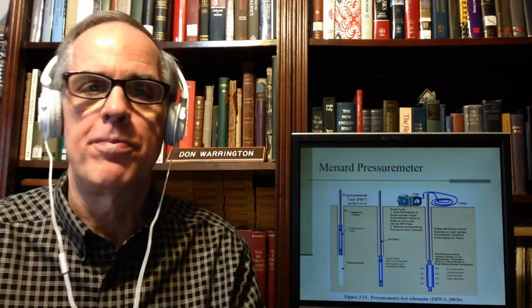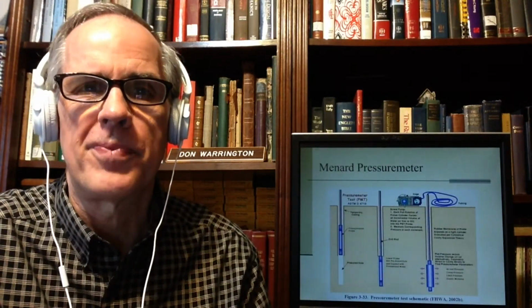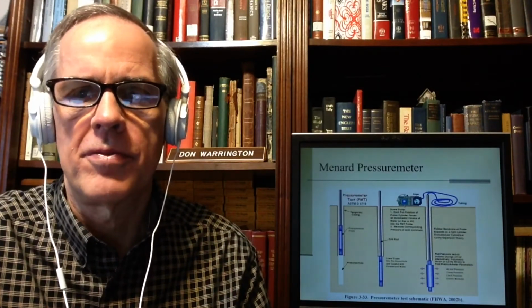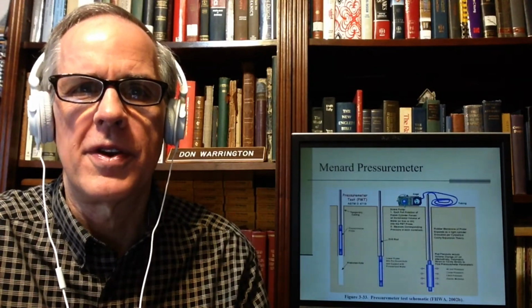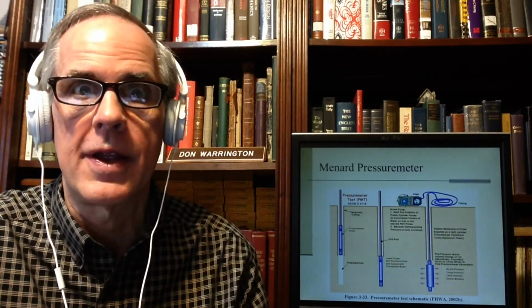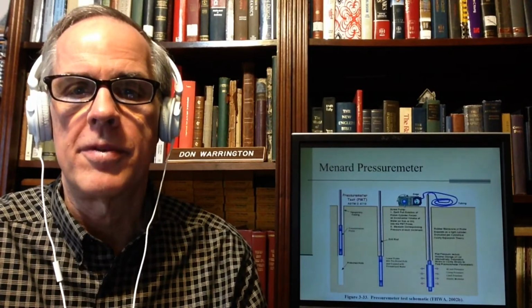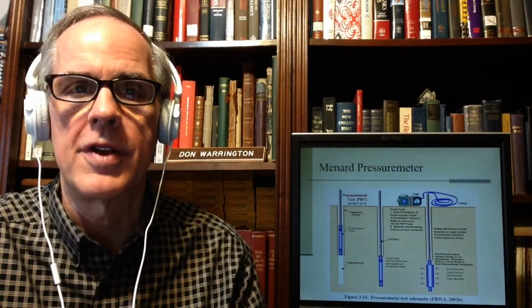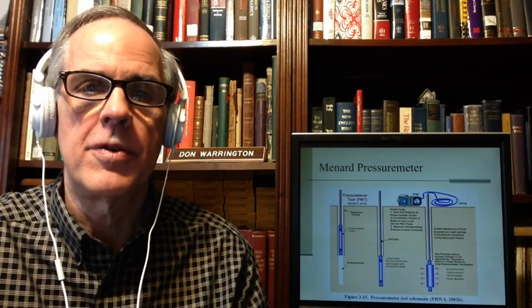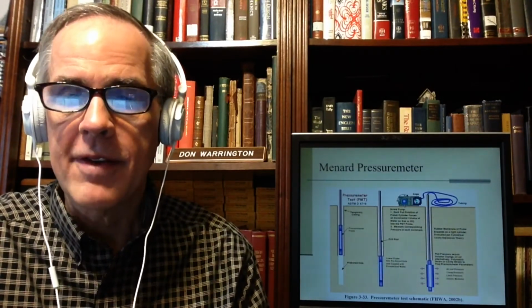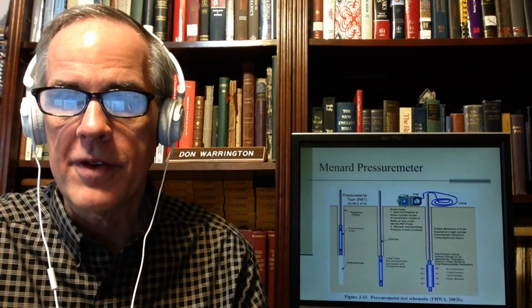A couple of specialized tests that you see more in sandy soils and looser stratigraphies, marine, coastal, that kind of thing. The state of Florida is big on both of these: the Menard pressure meter and the Marchetti dilatometer. The Menard pressure meter was developed in France by a gentleman named Menard. Basically what it is, it's really pretty simple.